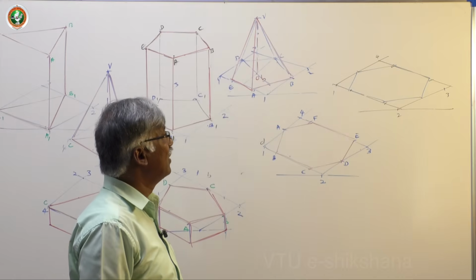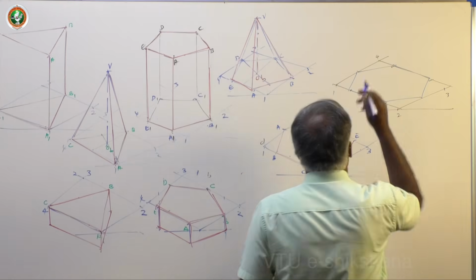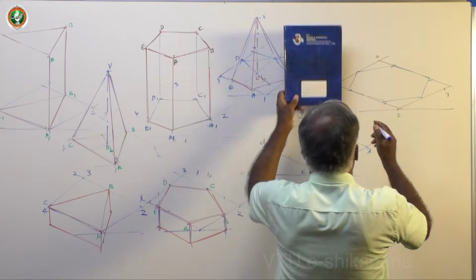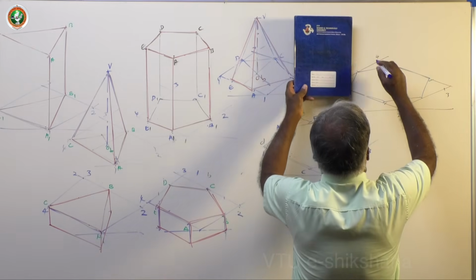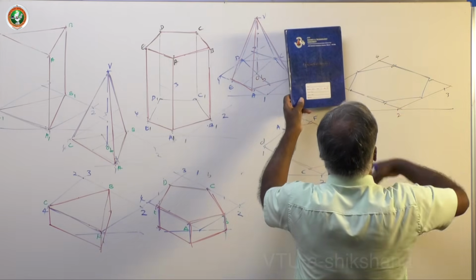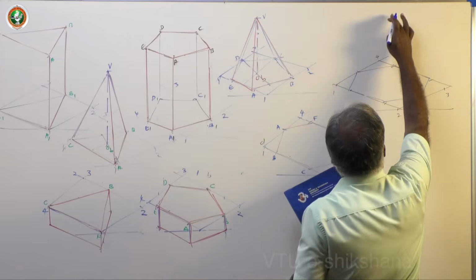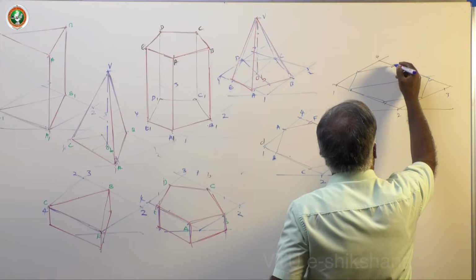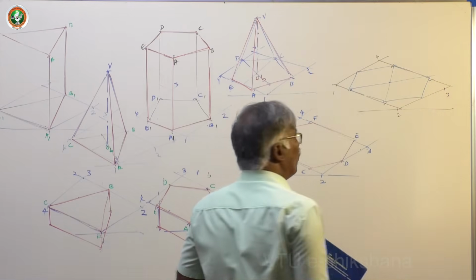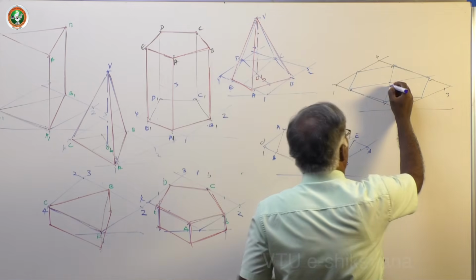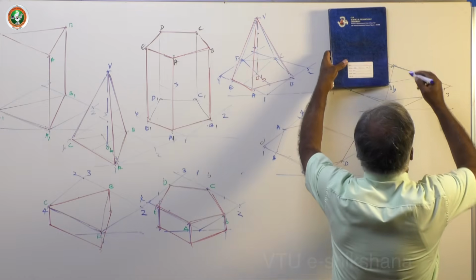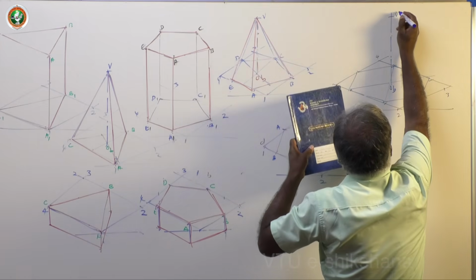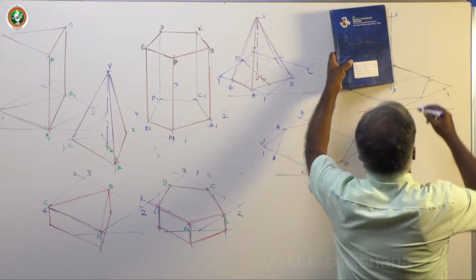Not worry. Now draw vertical lines throughout all distances. Okay, let me take up for this pyramid, then we will develop prism. Easy for me here. Location. Now let me develop first pyramid. Identify 2 diagonals. This is OB. Then draw vertical line. Fix axis V. Join all corners with V.